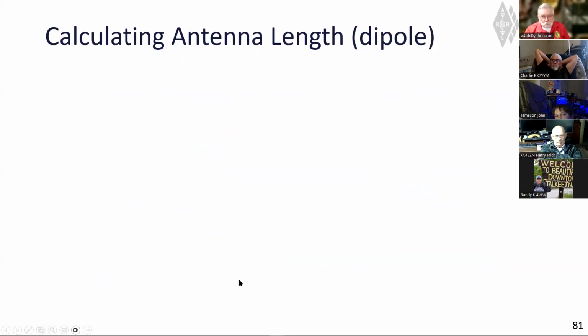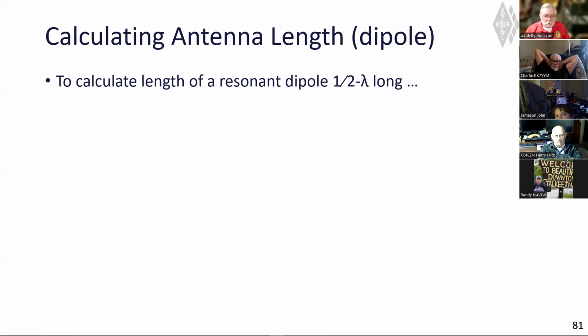One thing, when I was talking about my ground plane here, the radials that come off of it, the reflected plane, if you have a speaker mic on your handheld and hold the handheld away, the shielding on that mic cable acts as part of your antenna to help the radiation, acting more as that counterpoise or the other half of the antenna.